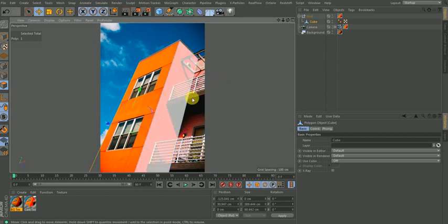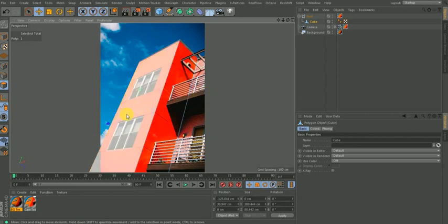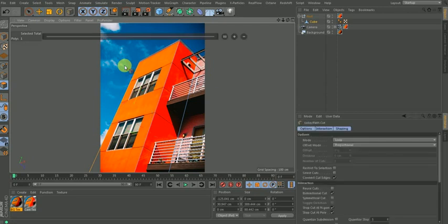So let's do this wooden slab. So I'm going to bring up my knife tool. The shortcut is KL. If you hit your K, you have three options here. By the way, I'm using Cinema 4D R19, so you have the three different options of knife tool. Either you want to use a plain cut, line cut, or loop. But what I want is a loop, so I'm going to hit L. So the loop cut is going to be around this surface.